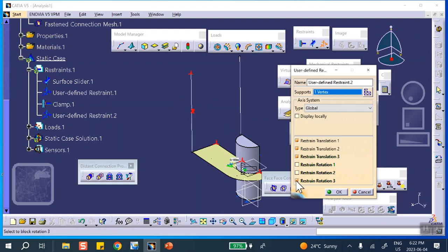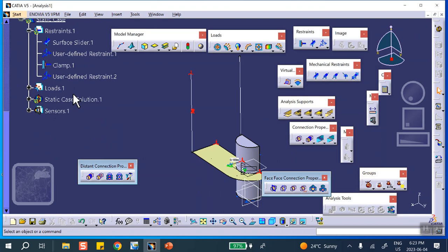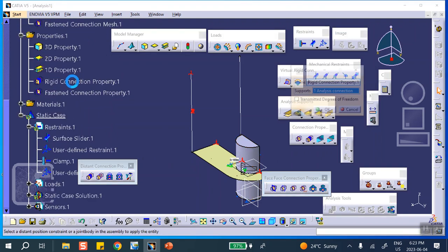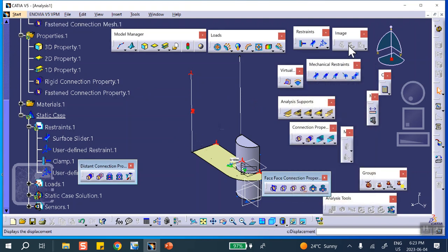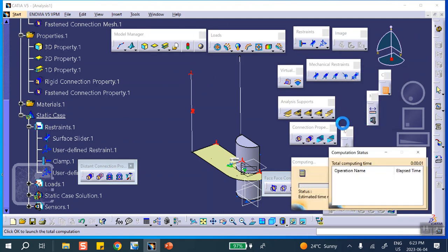So just to convince you, I'm going to uncheck that. That's good. And for transmitted degrees of freedom, you have to go to properties. That rigid connection, you check on the box, it says don't worry about rotations. Because we don't worry about rotation about Z here, and don't worry about rotation about Z there, it can spin and it will not run. You'll see.